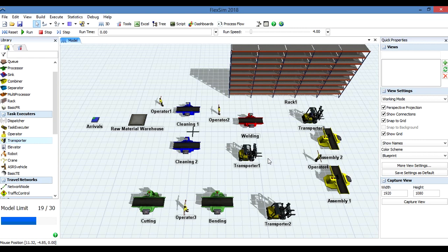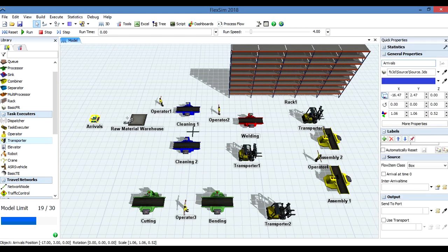Okay, we have now all the resources and elements to make our model work. Now we need to tell the software all the relationships to know the sequence of the item. We're gonna start by the source. Remember to connect objects or resources, that in this case are these icons and the stations, the different stations. We're gonna use the key A. We're gonna press on our keyboard the key A. We're gonna click on arrivals.